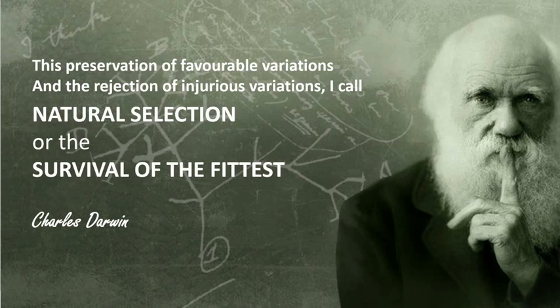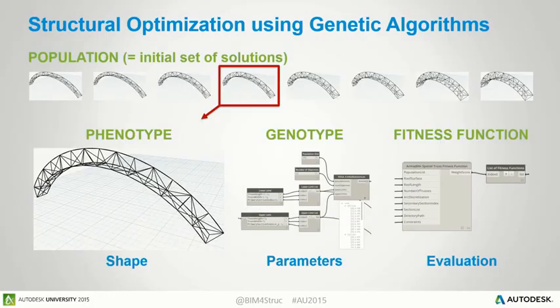And you see in the 2, 3, and 4th index, the 2 is the percentage of overstressed members. So we have almost 10% overstressed. 90% is over-designed, and 0% is within the range between 0.8 and 1. So that first design option, it's crap. I cannot use it. Okay?